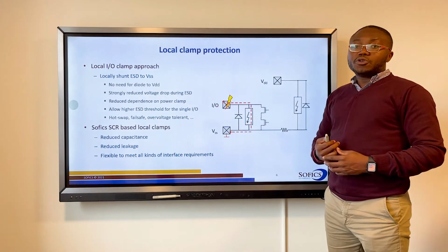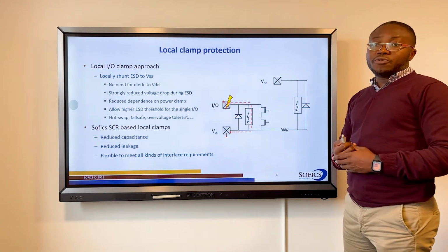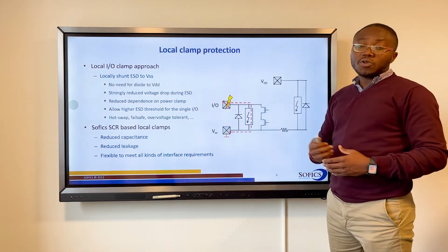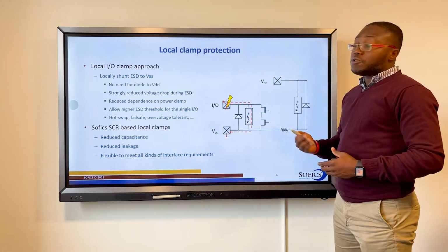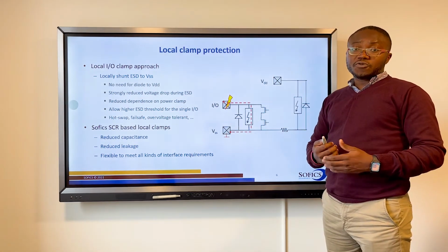The local clamp approach resolves all the issues of the dual diode approach by replacing all diodes with a single local clamp. The approach followed by SOFICS uses silicon-controlled rectifiers.